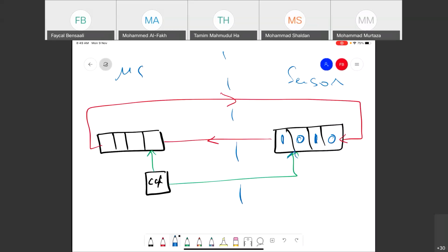This clock goes to all flip-flops, so every clock cycle the data will go out from one to the other. The data will be shifted. So if I put here the first clock cycle, what will happen? Assuming here we start with 0, 0, 0. After the first clock cycle, what do we have in the sensor shift register and what do we have in the microcontroller shift register?